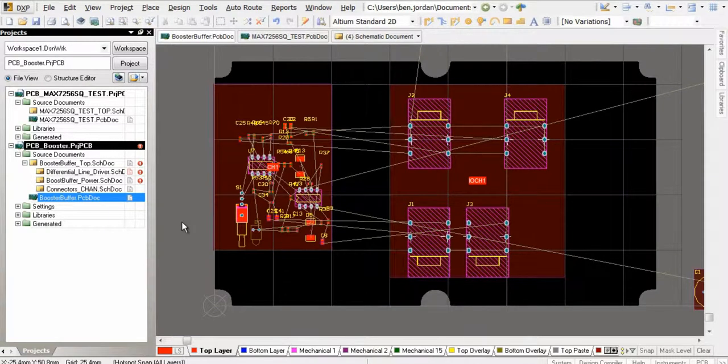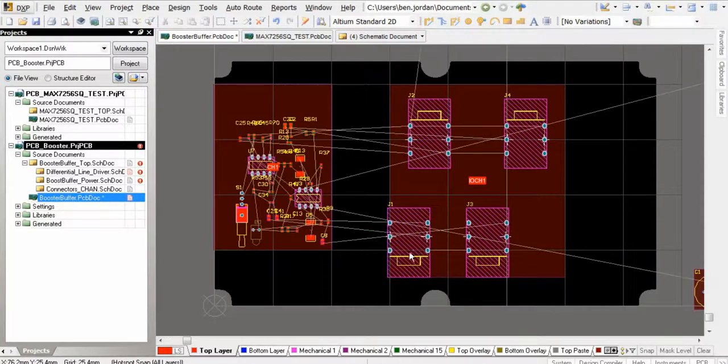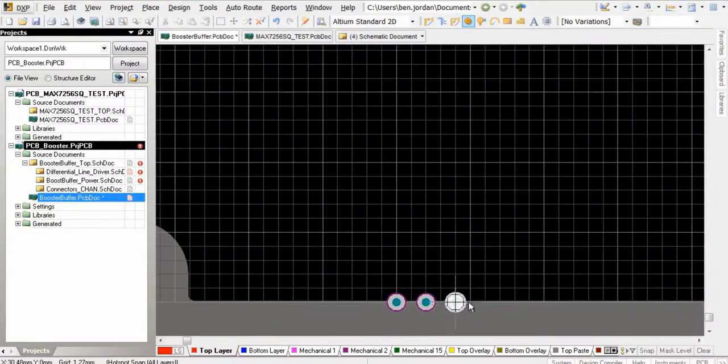In this design, I want to place an array of connectors which must align with this edge of the board, and another array aligned with the opposite edge. An easy way to do this could be to enable Snap to Board Edge in Advanced Snap Options, but for these connectors the reference point is the first through-hole pin, so it doesn't really help.